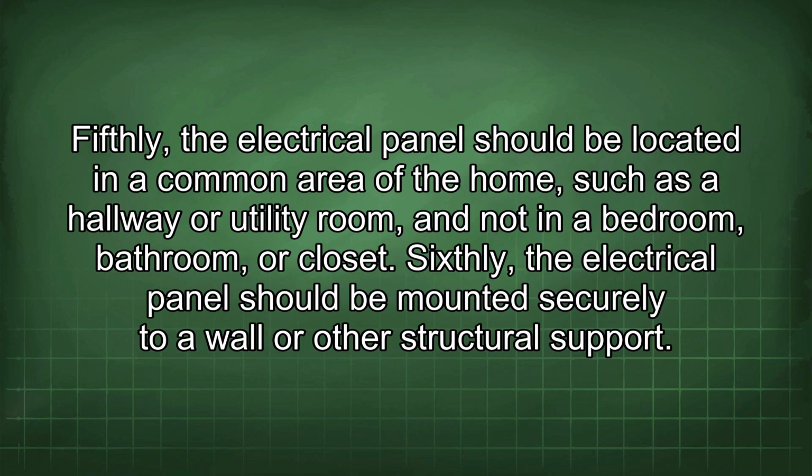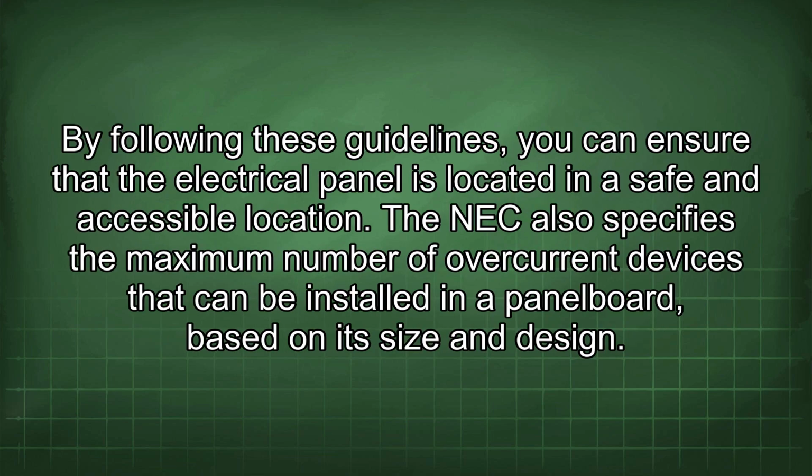Fifthly, the electrical panel should be located in a common area of the home, such as a hallway or utility room, and not in a bedroom, bathroom, or closet. Sixthly, the electrical panel should be mounted securely to a wall or other structural support. By following these guidelines, you can ensure that the electrical panel is located in a safe and accessible location. The NEC also specifies the maximum number of overcurrent devices that can be installed in a panel board based on